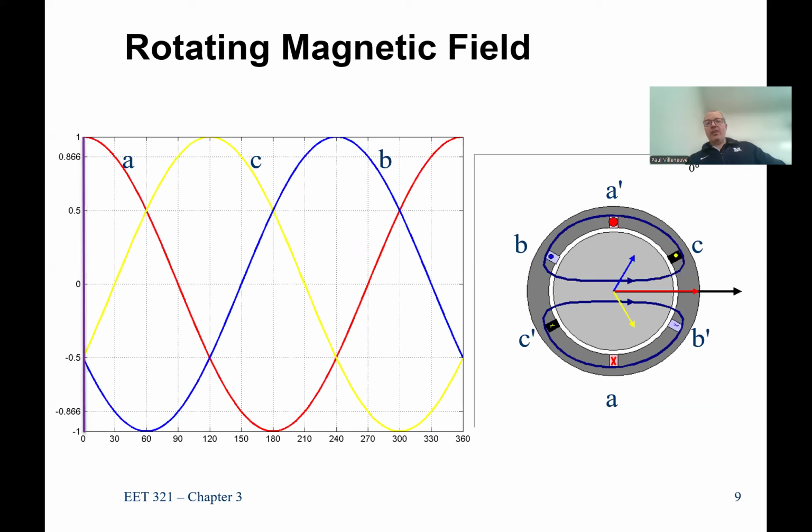So let's go over here. Look at A. The X, it goes in. My fingers point in. It wraps around because the coil of winding has to come back. It has to be a complete circuit. My thumb points to the right. So look at the red arrow in the center. It points in an orthogonal vector based on using my right-hand rule. Don't use your left.